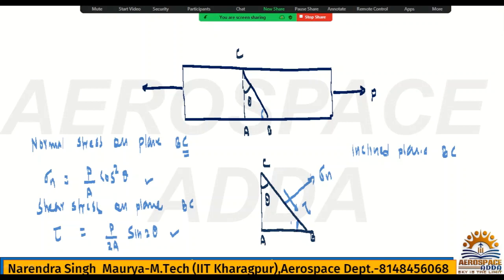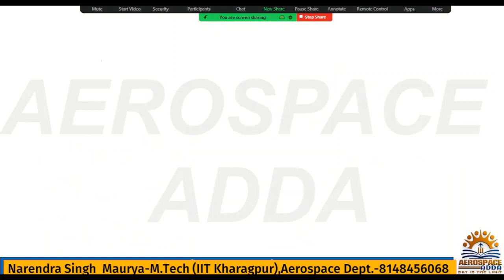Okay. All right. Now, if I want to calculate the maximum, because we have normal stress and shear stress on the oblique plane, what will be the maximum normal stress? Sigma n is nothing but P by A cos square theta.